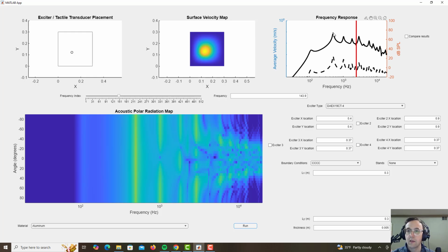So, we don't really have any bending motion on the panel until about 492 hertz. That's the first mode, that's this guy. And then you can see there's not really much radiation until 500 hertz here. And then even after that, we only really have radiation at these pretty sporadic little modes. And then the coincidence frequency happens right here, and then it starts to beam. That would be not a great sounding speaker, to be honest. Not good at all.